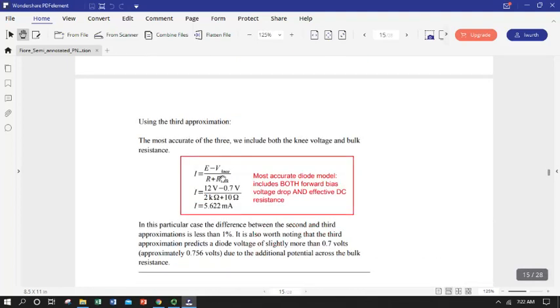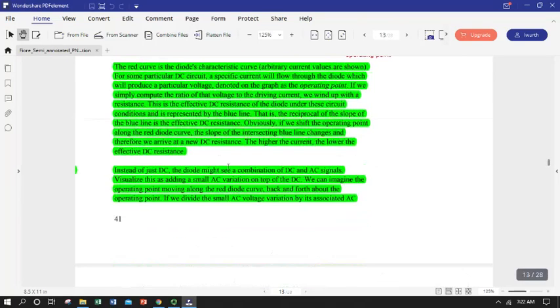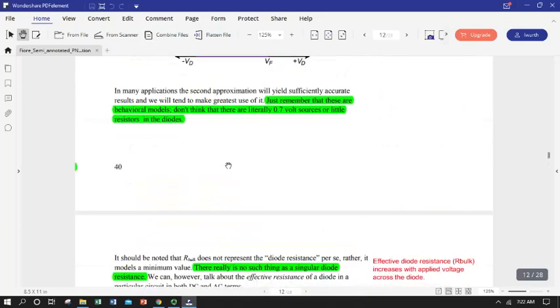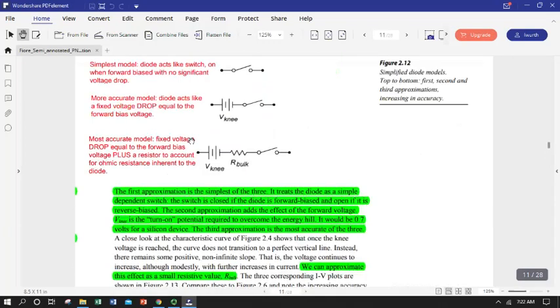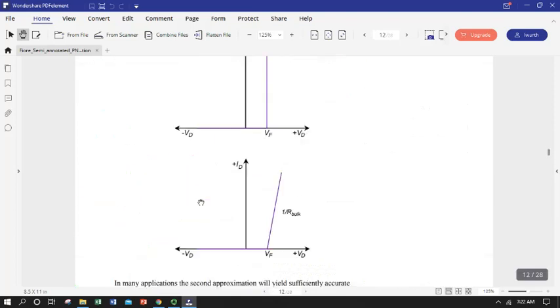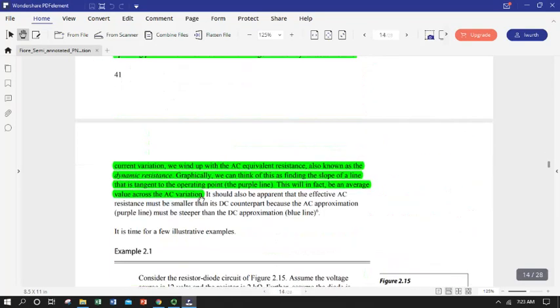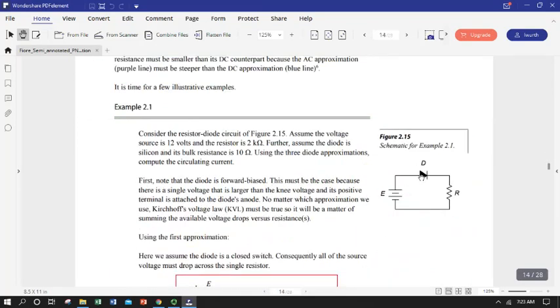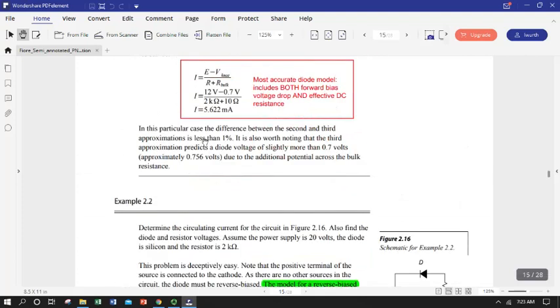And of course, if we want to add the series resistance of the diode, it can just be lumped in with the other resistor because they're both in series. But our total driving voltage of the circuit is still discounted by our voltage source, and that is using, go back up, that last one is using this model. Okay, with the switch closed. With the switch closed because the diode is oriented going forward.